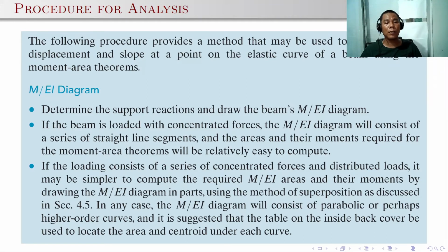You can draw the M over EI diagram in parts using the method of superposition as we have described before. In any case, the M over EI diagram will consist of parabolic or perhaps higher order curves, and it is suggested to use the table in the inside back cover of the book by Hibbeler to locate the area and the centroid under its curve.